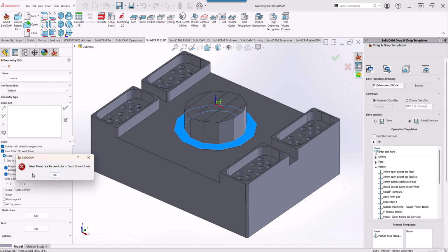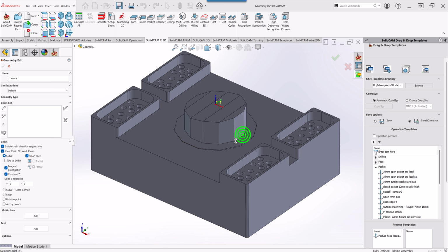Click on it, and you'll see that the plane is not perpendicular to the z-axis. And if I try picking an edge, this edge is not constant z around all faces. So it'll only take that edge, and when it gets over here, since this is not on the same z level as this, it's actually tilted down, it will not pick it up, and it will wait for me to pick another edge. I'll click on that one, the same thing will be with the next edge, and so on and so forth. So a constant z cannot be picked on this edge.